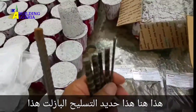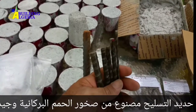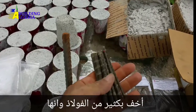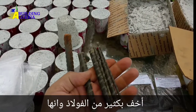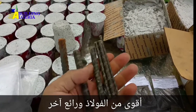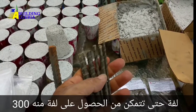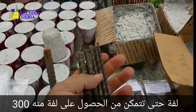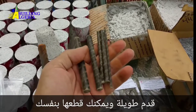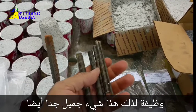This is basalt rebar. This is rebar made from lava rock, and the good thing about this is it won't rust. It's much lighter than steel, and it's stronger than steel. And another great benefit is this stuff will come on a roll, so you can get a roll of it 300 feet long, and you can cut it to your own length, whatever length you require on the job. So that's a pretty nice thing.